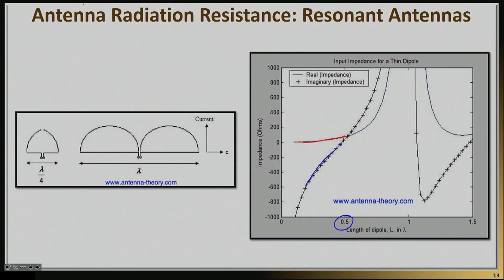And that will be essentially the resistance that you have to match with a matching network when you design this antenna. Now, what is also interesting to notice about a resonant antenna like the dipole is that away from resonance, the reactance of the antenna actually changes dramatically. That's a direct consequence, of course, of this being a resonant antenna, meaning it works well only at its design frequency. And away from it, it develops a very high value of reactance, which means it becomes very, very difficult to match those antennas.